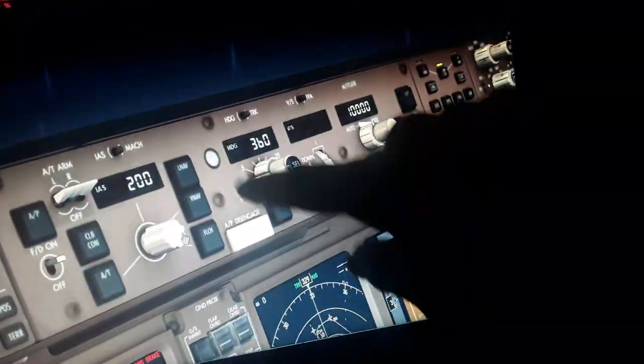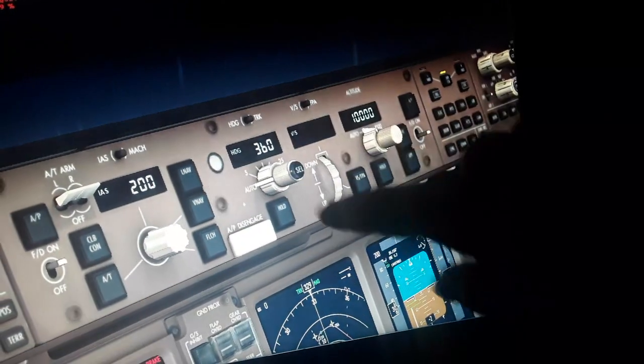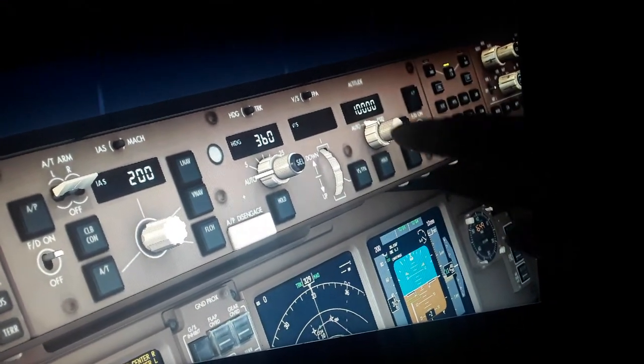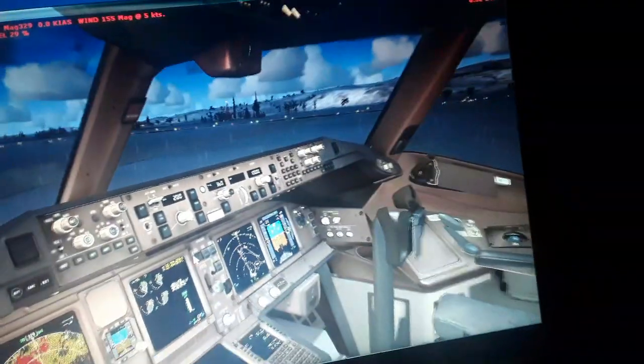So this is the airspeed selector right now, and we have the modes around it. You can see also the heading guidance, the airspeed guidance, the vertical rate of climb or descent of the aircraft, and the altitude. And we have also the roll localizer and the approach for the autoland function.